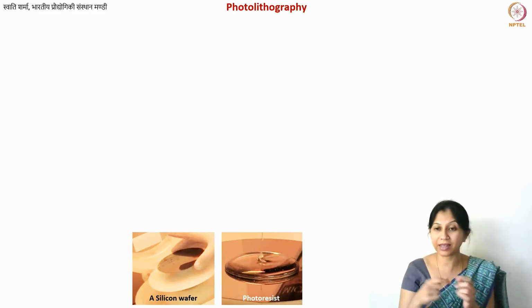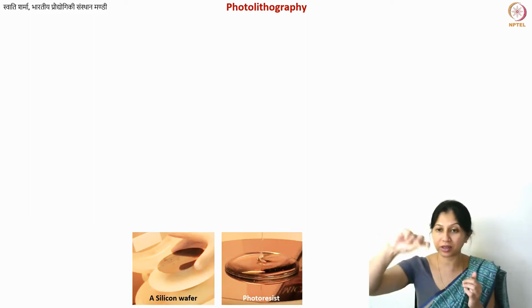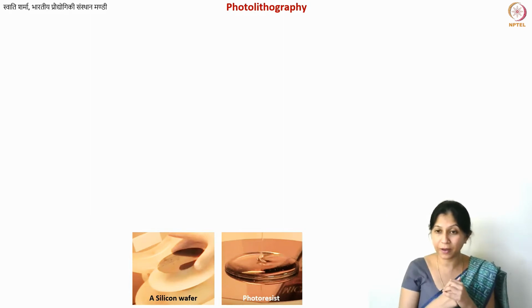And after that, in the second image, you see that there is a photoresist being poured on top of it. And this resist, as you can see, has a reasonably high viscosity. You can also get lower viscosities. So after pouring it, I will spin coat it at whatever RPM, let's say 3000 RPM, and then I will get a certain film thickness.